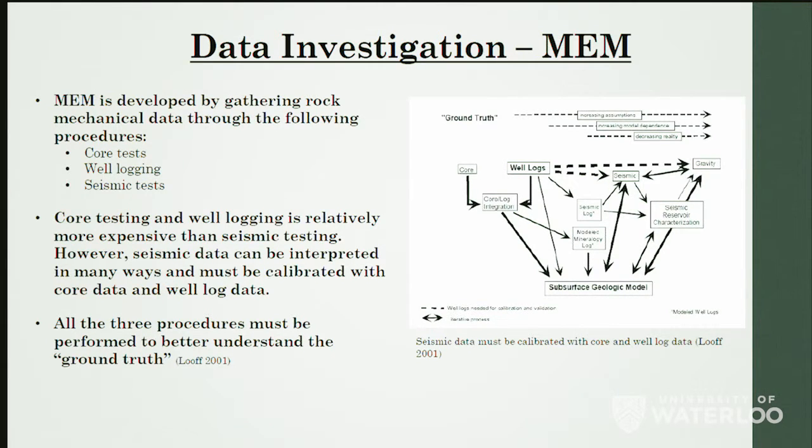So to get a better picture, or to get a better ground truth, we need to actually perform all these 3 kinds of testing. And even though core testing and well logging are relatively more expensive than seismic testing, they still need to be performed because they are needed to calibrate seismic models. Seismic testing alone will not produce adequate results.